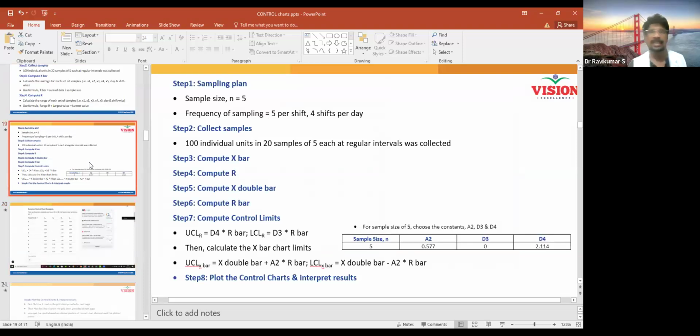Every time when you collect data, you know how many times you are going to do the inspection. For example, let us take a food industry, where packets are being packed. Out of 100 bundles, they are collecting 10 bundles for checking. So sample size is 10. Similarly, you will be collecting samples in every industry. The sample size decides the constant value for the X bar R chart.